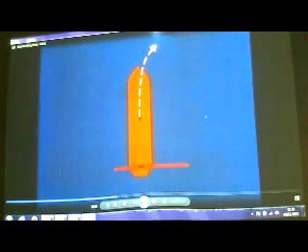This variation of the velocity of water entering the propeller disc changes the relative angle of incidence to the rotating blade. The red arrows show the resulting imbalance of drag forces in the upper and lower sections of the propeller disc. This will tend to turn the ship to starboard.